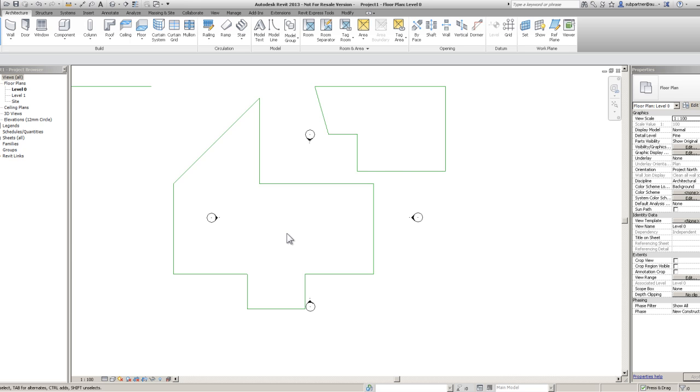Now, when you've got a chain of anything, in this case we've got model lines, but this can be the same for pipes, walls, boundary lines, lots and lots of different things. Whenever we've got anything that has been drawn in a chain and they're joined at the end, this works like this. If I hover over one of those lines or walls or pipes or ducts, anything that is part of a chain, if I simply hit my tab button, don't hold it down, because if you hold it down, what happens is this.